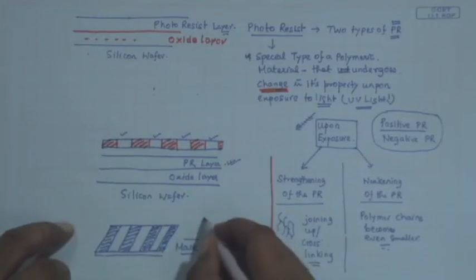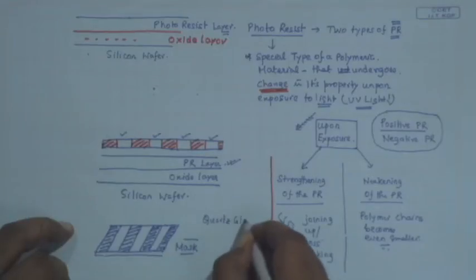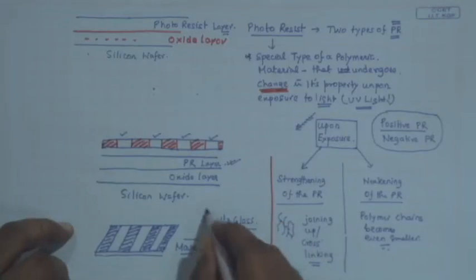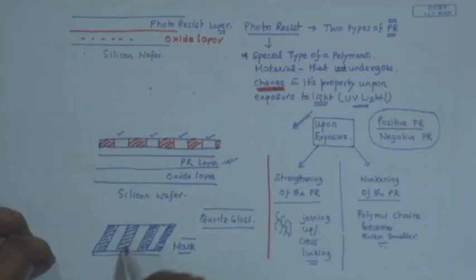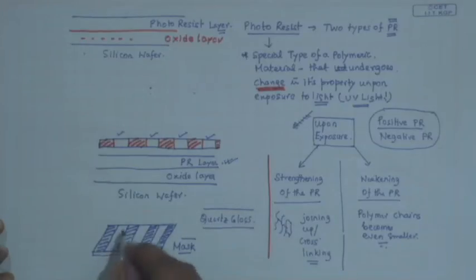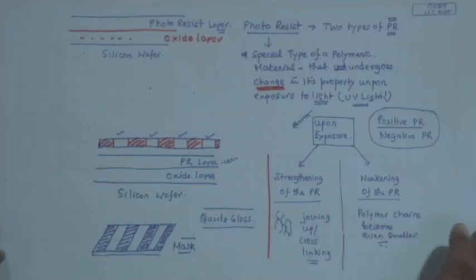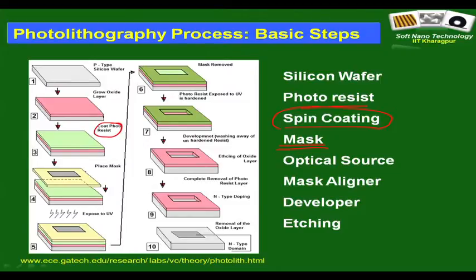Typically, one takes a piece of pure silica glass or quartz glass, and chromium is a very good absorbent of UV light. So, these patches are created of chromium. Again, this is a fabrication issue. Yes, you need some microfabrication platform. What you typically do is take a glass that is fully covered with chromium and then etch out some of the areas so that the light can pass. And so, you now start understanding one more step in this flow diagram.